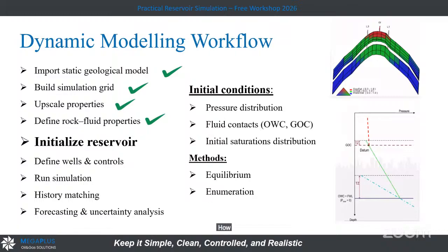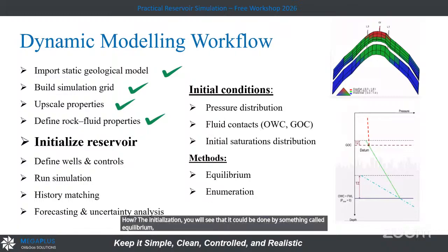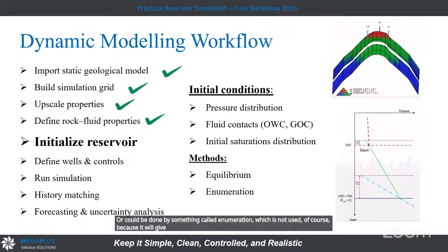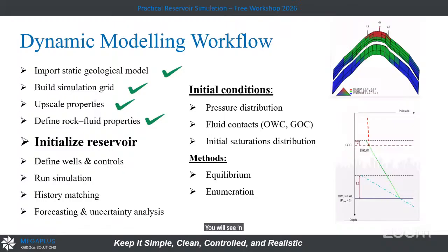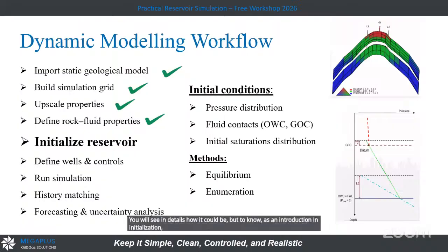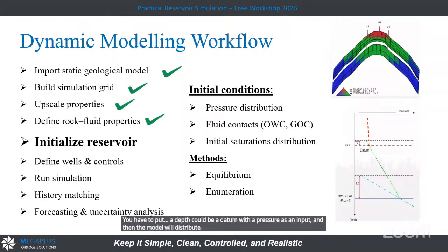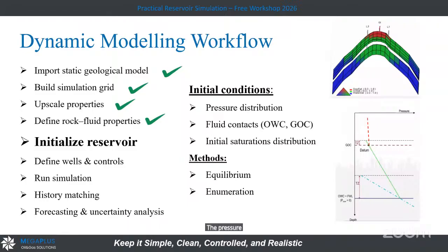You will see that it could be done by something called equilibrium, or by something called enumeration, which is not used, of course, because it will give a lot of errors. To know as an introduction, in initialization you have to put a depth, could be a datum, with a pressure as an input, and then the model will distribute the pressure vertically up the datum and down the datum.